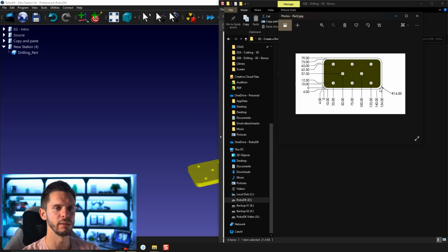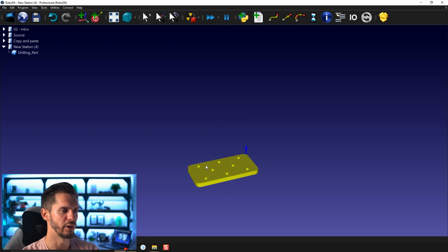Here, using Move C's in the corner, I purposely did not give you any transition point. I only gave you the radius of that corner, so you need to extrapolate the intermediary point. So the goal is to come in, drill the 8 holes, and then do a path around to finish the exterior of the part. So the part is here. Those are the two parts you can practice on.